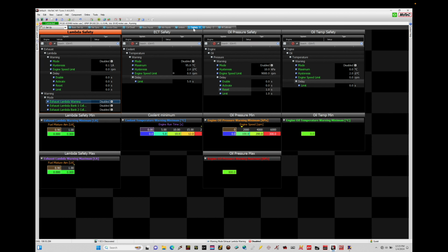Well, when we're setting up a warning option, this would be on a particular channel where we want to have some indication that something may be out of place. A condition might be getting to a concerning range or level, and we want to be warned in the software. We'll find that we can get our warnings. They appear down here in a flashing red bar. We toggle F3, we can see what the status and diagnostic is going to be. That'll be where we find the warning, and I'll demonstrate that here with a couple different variables. So we have a warning option. It'll give us a heads up that there's something that's getting out of range or out of place.